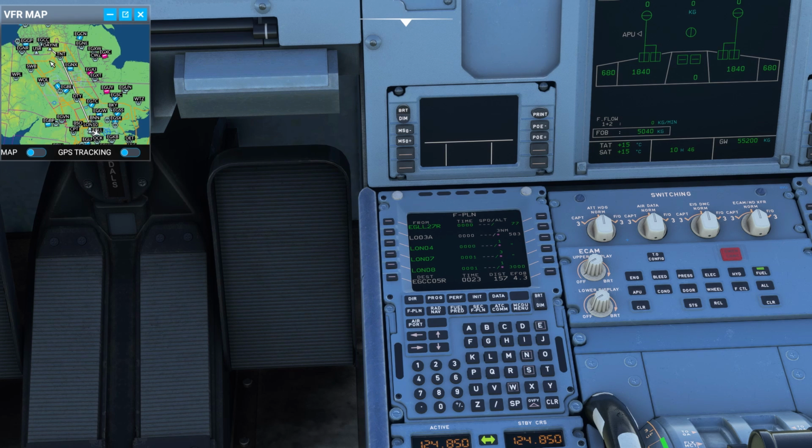It's a very basic flight plan there. I have got one more waypoint that I need to hit that hasn't been selected, and that is the Welling waypoint. So I'm going to enter that in now. So all I'm going to do is scroll down to the point where I want it to be. So it needs to be in between umlaut and TNT.